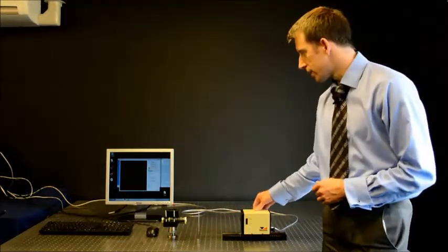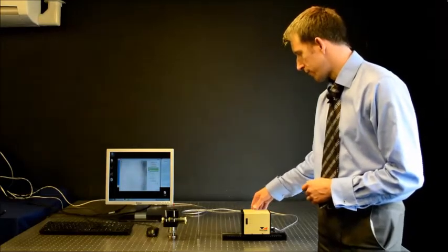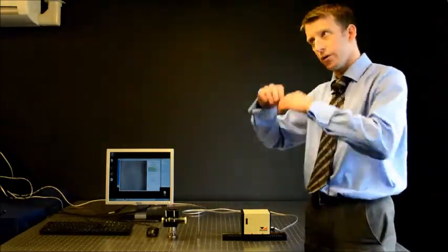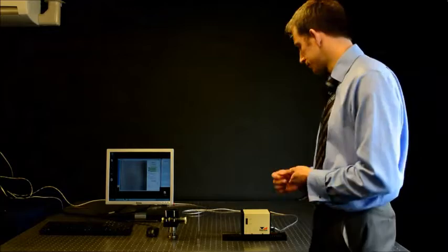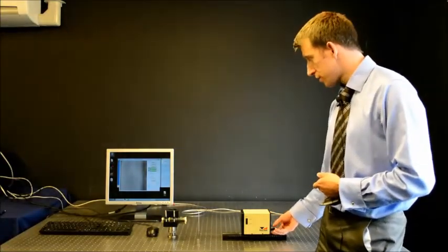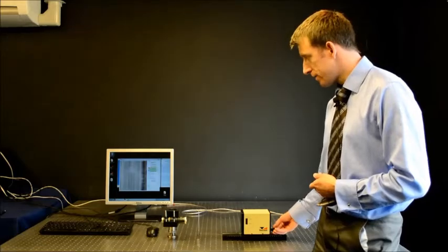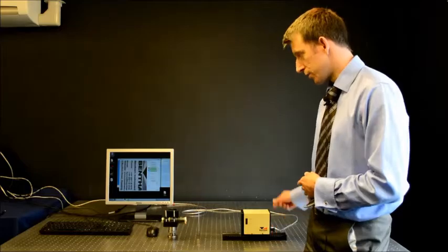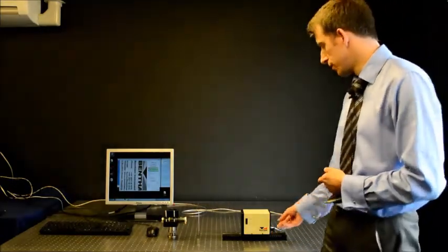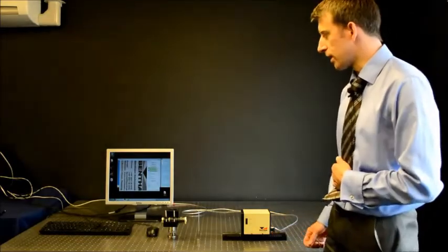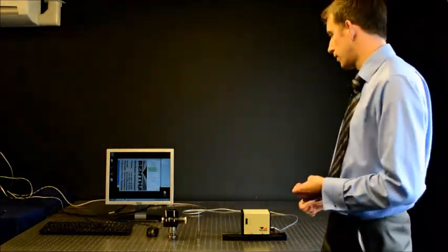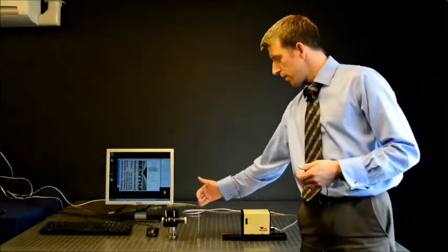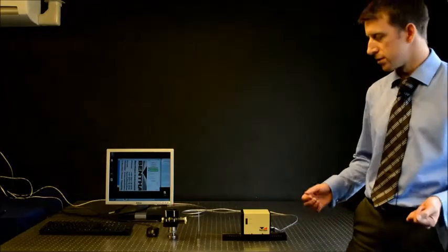If I open the ND filter wheel, I will have a view with no attenuation of the card illuminated by background lighting. I can adjust the position of the second lens to obtain a focus, and it will be shown in a subsequent software video how this is obtained. We can see here a good focus of the business card. So we can say the PSL Profiler is now focused on a position 200 millimeters distant.